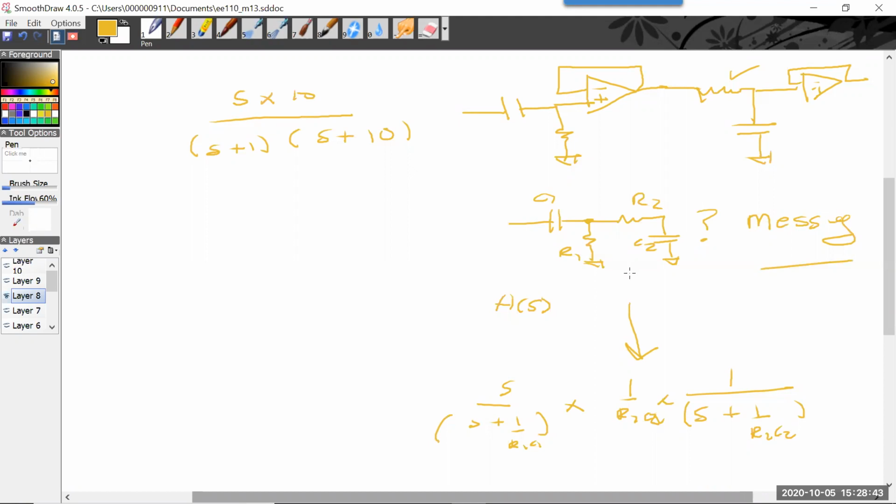But you might say, who cares? I'll just program it in Python. But what happens is that as it gets messy, this pole and this pole start to depend on every resistor and capacitor in the circuit. And the op-amp isolates it. The op-amp makes it so that we can easily synthesize. But sometimes you really have to get rid of an op-amp or you can't, and then you'll deal with it and you'll do that.